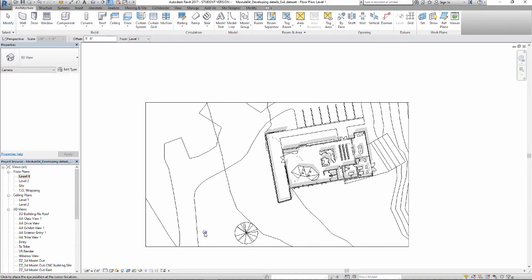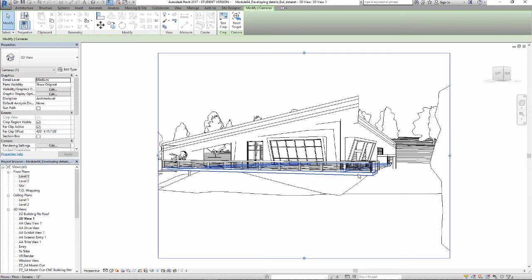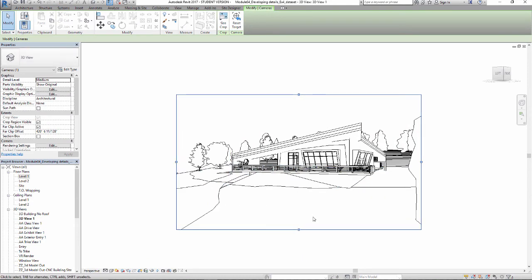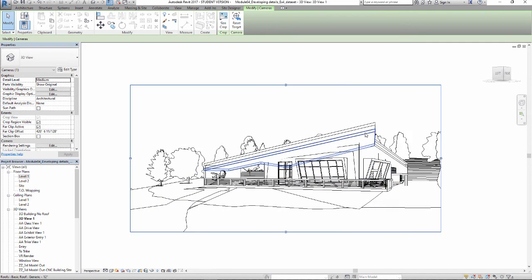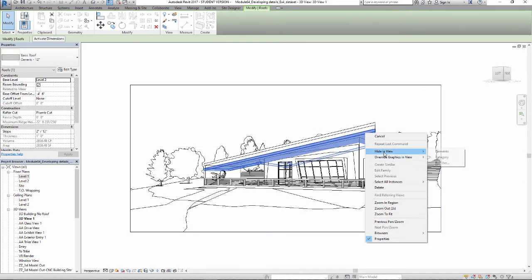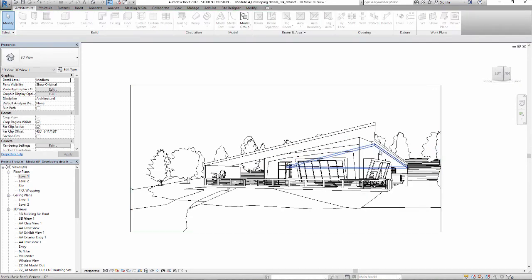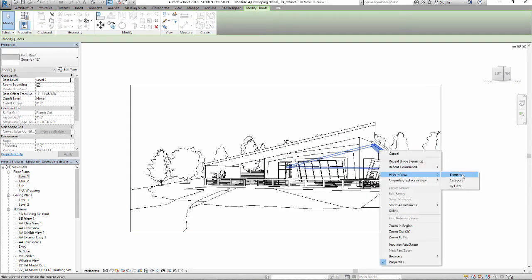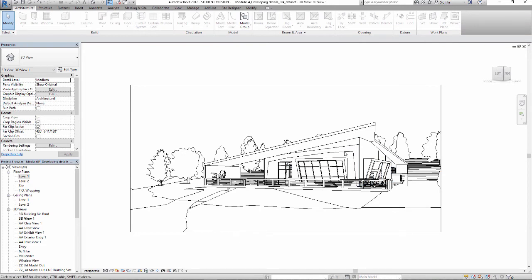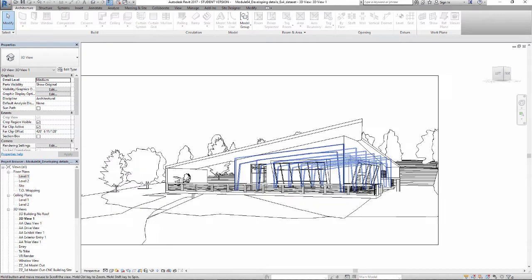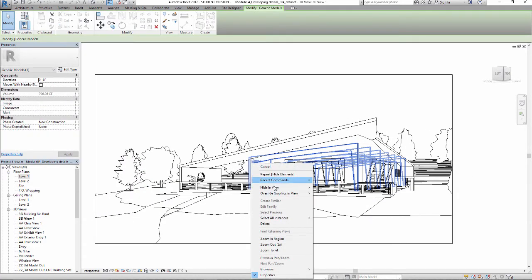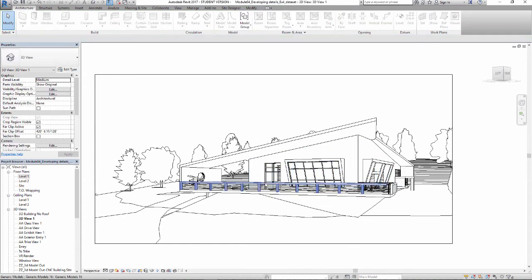And I'm going to set it up just like any typical exterior perspective as a camera view. And I'm going to send it a little bit across and reshape my bounding box just a little bit. And quickly removing or hiding, I should say, some of the elements that I don't want in the view. Let's get rid of this little structural system here. That was the foundation. There we go. A little bit tricky to select that dude. Okay, that should be good.